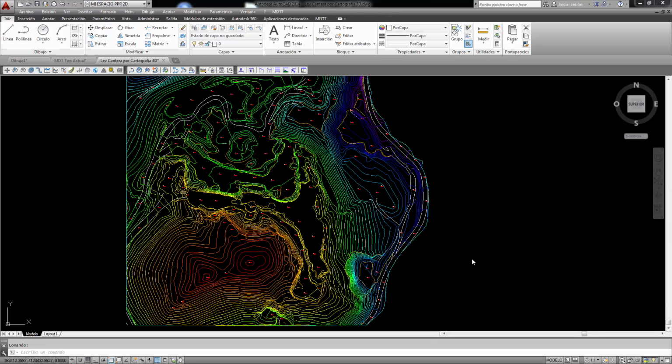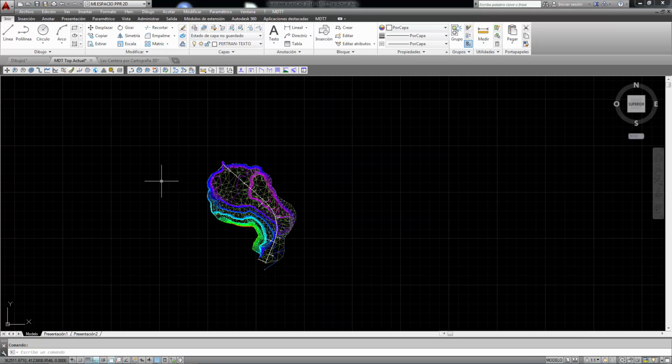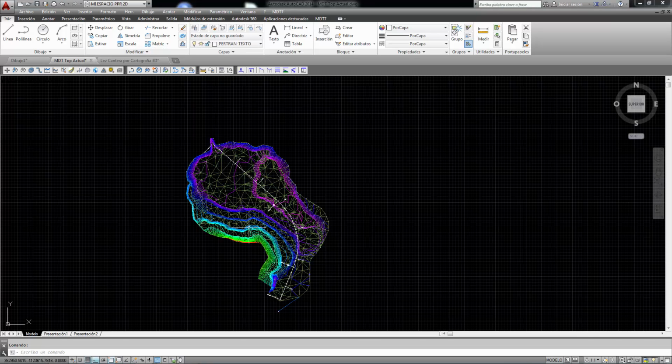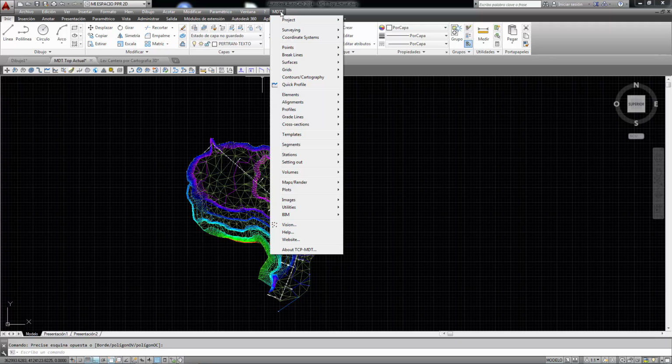We have the data calculated in the previous unit, the curvature and profiles, axes and cross profiles, and we are now going to proceed with how to calculate the volume of earthworks with our data, for which we use the surfaces we calculated in the previous measurements and the cross-section profile files, taking into account that the calculations should always be conducted using the same.